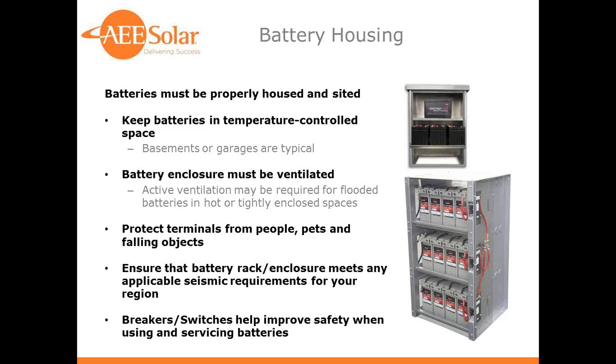Battery enclosures must be ventilated. Active ventilation may be required for flooded batteries in hot or tightly enclosed spaces. If there's a lot of gassing in the batteries, you'll get corrosion if you don't vent it properly. A 2-inch pipe going straight up and out the roof, or up and then out through a sidewall, as long as it's much higher than the battery compartment itself, will evacuate most of the hydrogen gas.